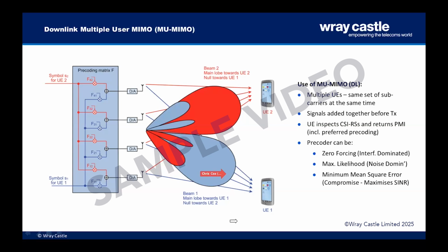At the same time, using our digital beamforming techniques, we are going to arrange for a null of the blue beam to be directed towards mobile number 2 at the top right, so that mobile number 2 picks up no interference at all.